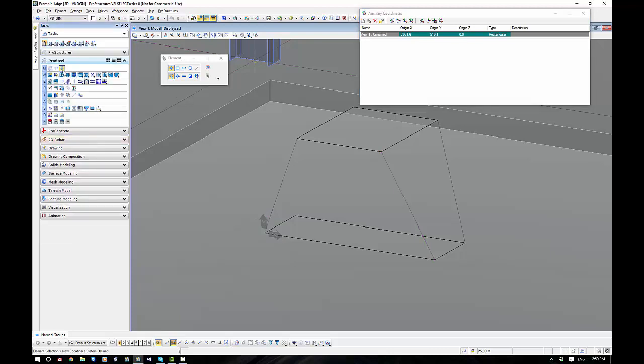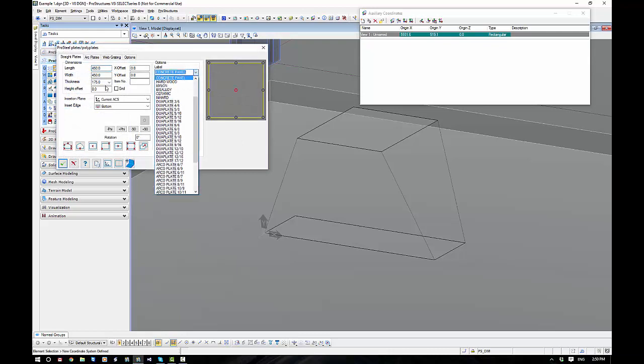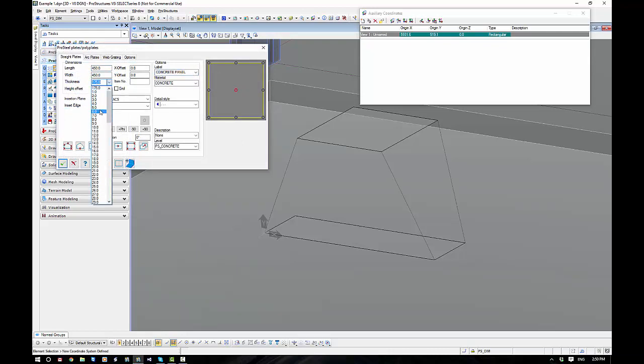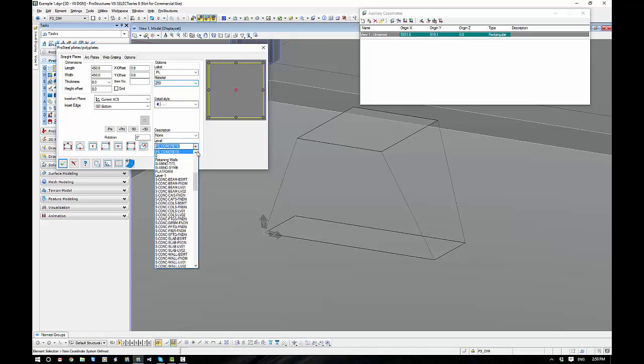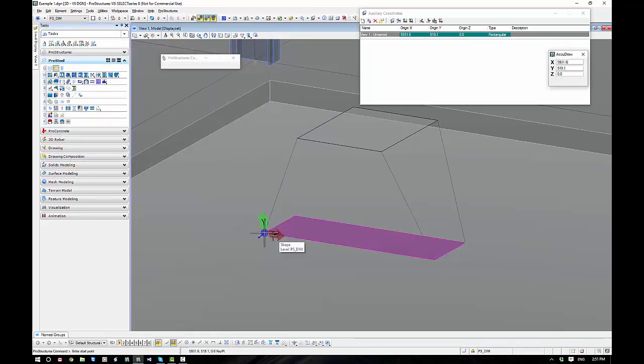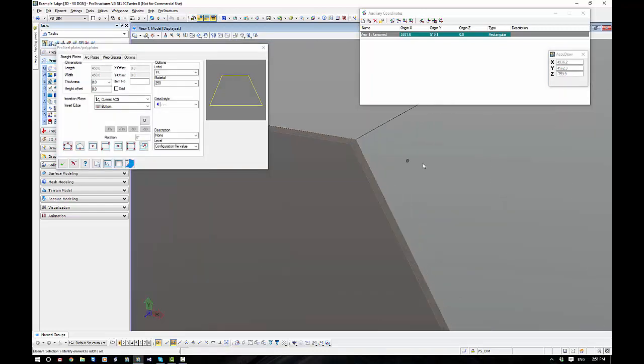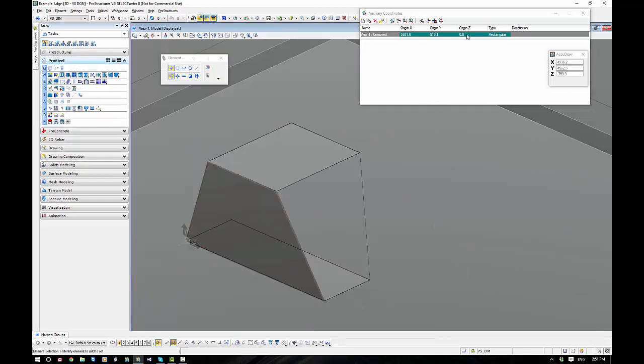All right, so I can just come up to my plates. Let's go 8mm plate. It is a plate this time. The plate material grade would be grade 250. Okay, we can set our level to the configuration value. All right, and I'm happy with that insert edge. So I'm going to select by points this time, and you can see that I'm going tentative snap, accept, tentative snap, accept. And we've got a little close button up there. In our panel goes. Really nice and simple.